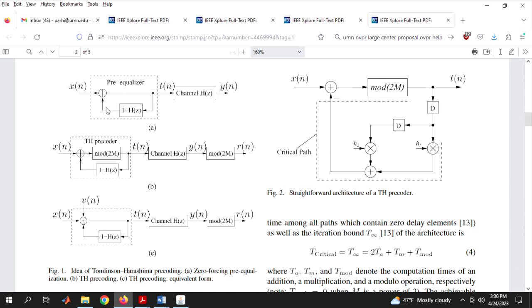Precoder means we pre-code or pre-equalize, and if you look at this transfer function, 1 over 1 minus the loop gain, where 1 minus the loop gain is h, then 1 over h, and the effective transfer function of that so-called pre-equalizer is 1 over h. 1 over h is simply trying to overcome the effect of h, and h multiplied by 1 over h is simply 1, or in the time domain is delta n, which means that we are able to get the transmit signal x n at the receiver.